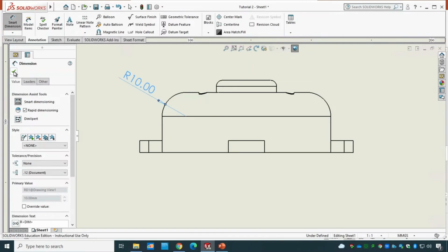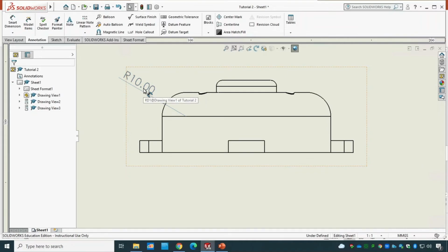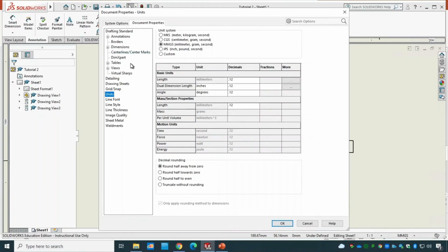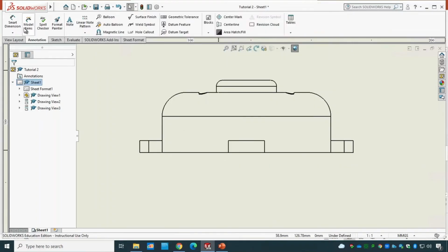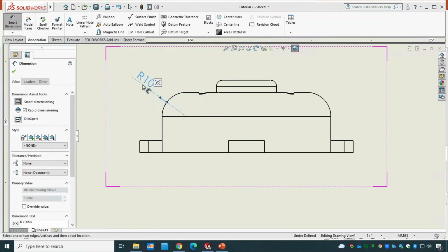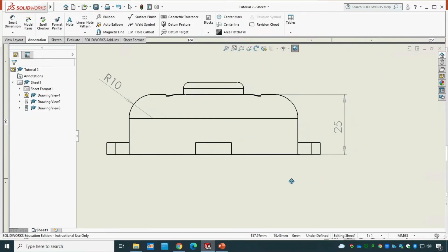And hopefully remember, if in case you don't want to every time go there and change those decimals, which in this case we don't need, let me get rid of that. I can easily go to the settings, go to the dimensions, switch off the precisions and click OK. Now anytime I go there and get the dimension, I no longer get that number out of it. So that's R10 in here. And the height of it, the distance from here to there, is 25. And that's it for this one. I'm gonna go and move on.